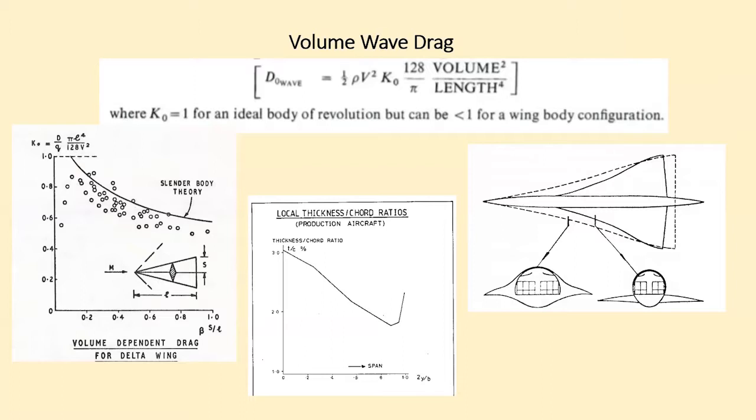They wanted to have an integrated configuration because it gave a low value of K. Our argument was that a low volume configuration, as we have on Concorde, was actually a better bet, even if it did have a higher than theoretically possible K, we still got a lower drag out of it.